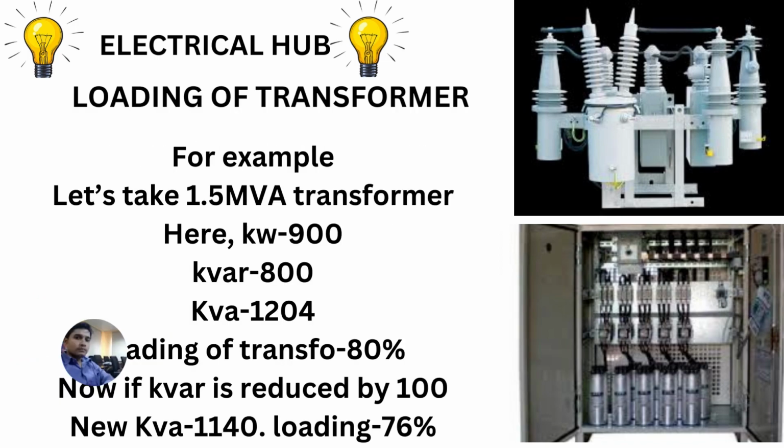Loading of transformer. For example, let us take a 1.5 MVA transformer. Here, kilowatt is 900, kVAR is 800, and kVA is 1200. So, the loading of the transformer is 80%.